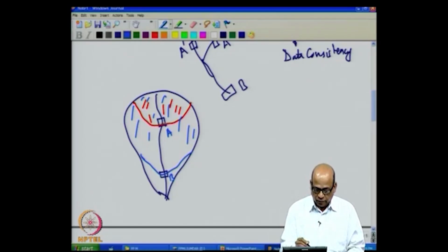Now, this flow has taken place because of the catchment that is marked in red here. So, all of this catchment has contributed to the flow at that location for a particular annual rainfall. So, that annual rainfall has contributed to flow at this location, and that is some 500 million cubic meters or some such thing. If you divide that annual flow by the area, we get what is called a specific flow.